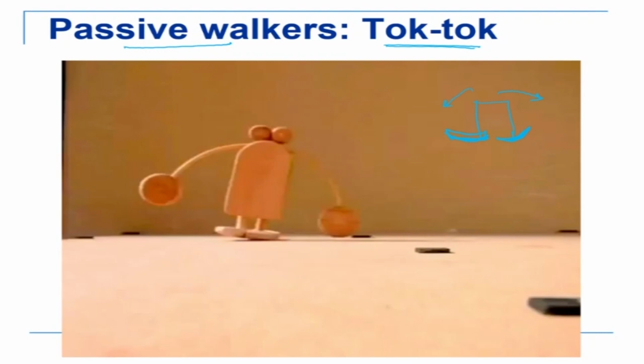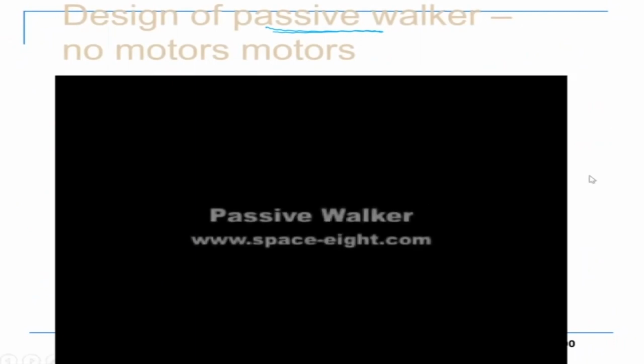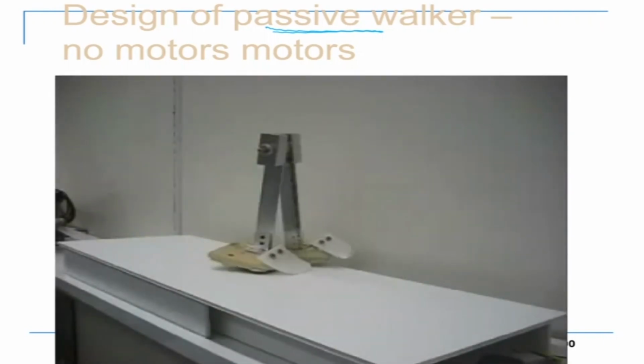So the shape of the leg, if you look at the passive walker that we have shown here, it's semicircular here. Notice very carefully, in this direction and also in that direction. Okay, so this is my leg. It's like part of a sphere. Okay, that is the shape. So it can bend on that side and it also rotates on this side. So if you look at this passive walker that was walking, you'll notice that it is actually bending from side to side and also rotating or rolling in the front direction. Okay, so the legs are a part of a sphere.